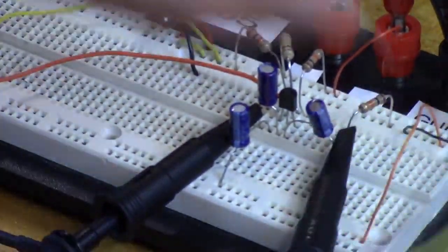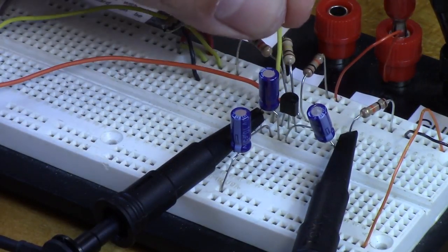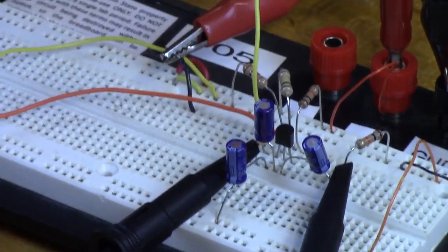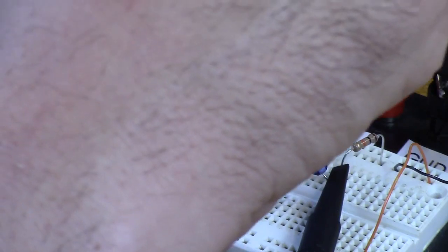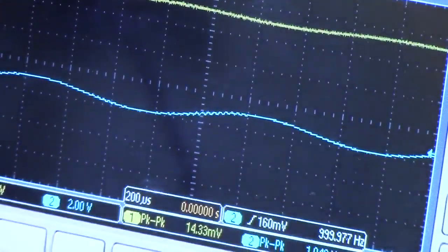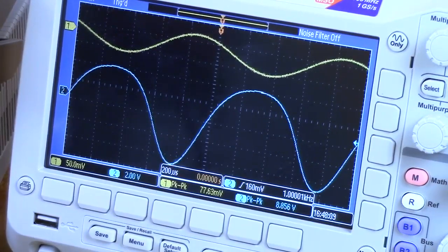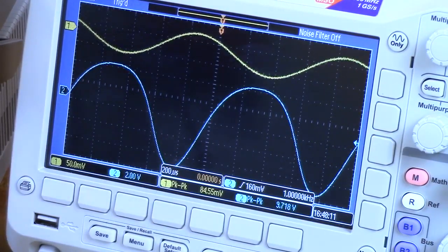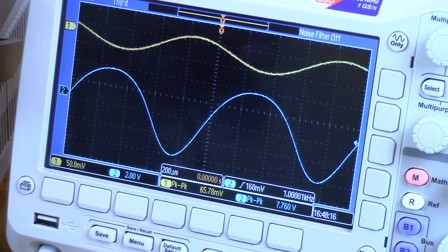Okay, so now we are free to unplug RS, the 1K resistor, and we're going to plug in the pot using the center lead and one of the side leads. Let's center the pot before we plug it in. Okay, and put that back. And what we're going to do is turn the pot to 0. Make sure we still have our 8 volts coming in there. It's actually a little bit more now because the RS, the 1K, is gone. Let's crank that down until we get to about 8 volts.